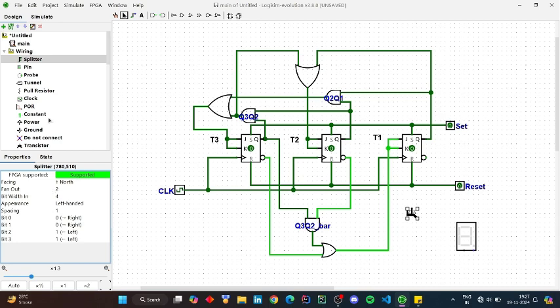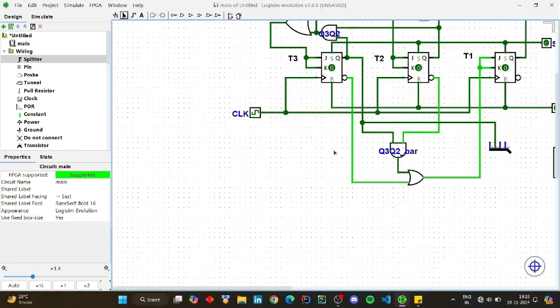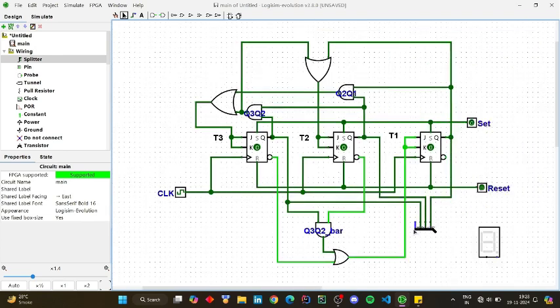We can change it to 4, and then change the fan out to 4, because these two values must be the same. Not in all cases, but mostly they should be the same. We can ignore the third terminal and connect T3 T2 T1 to the second, first and 0th terminals of this splitter. Let me make it real. For the final terminal, the one which is third, we can just connect it to ground, since we don't need that.